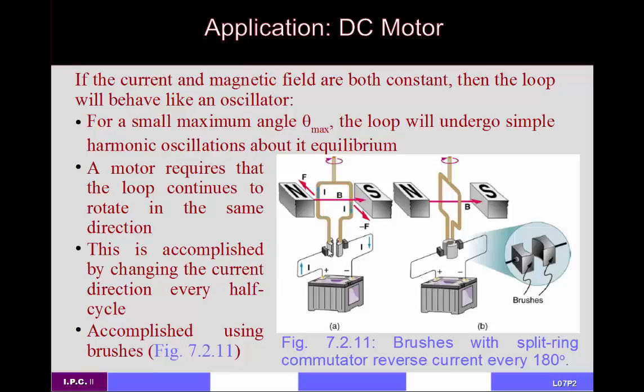For what it's worth, these split conducting contact pieces actually have a name. They're actually called a split ring commutator. You can see why it has that name of split ring, because they look like you've made a complete ring around and then chopped off two sections of that ring. And so the split ring commutator is what makes this DC motor actually work.